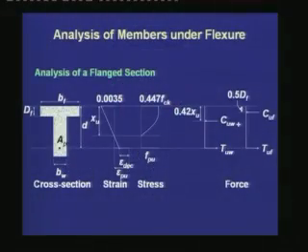In our last lecture, we had seen how to calculate epsilon DEC, and the expression is different for a pre-tension beam and a post-tension beam. In an analysis, epsilon DEC is given from the value of the prestressing force. Now, once we know epsilon DEC and the strain in the concrete at the level of the CGS, we can calculate epsilon Pu, from which we can calculate the stress FPU from the design curve of the prestressing tendon.